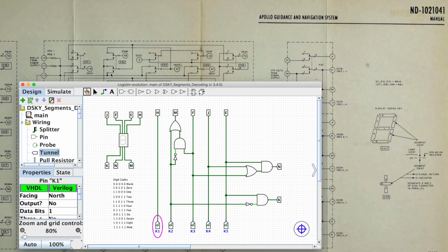If you look at the second relay, it gets interesting because it powers M. When it's down, it will be connected to 250 volts, so it will be powered up. Here I have the segment M lit up. But if it's off, there is another path that goes here, and it will be powered if K3 is on, which I have reproduced here. So M is either K2, or not K2 and K3. If I do this, it will also light M over here, and the bottom contact of K3 lights up F, I believe. Yeah, right, this is F. So it lights up 2 segments, F directly and M indirectly.